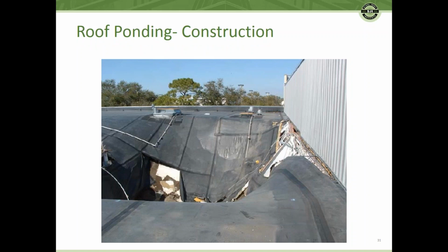Also, I've seen at least 3 instances where, when you have a membrane roof system, the installers put the membrane down and then take the drain unit, fasten it down through the membrane to the deck, and then cut the hole in the membrane for the inlet.